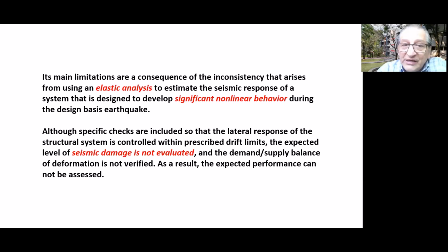Well, its main limitations are a consequence of the inconsistency that arises from using an elastic analysis to estimate the seismic response of a system that is designed to develop significant nonlinear behavior during the design basis earthquake. See, elastic analysis to estimate nonlinear response or nonlinear behavior.